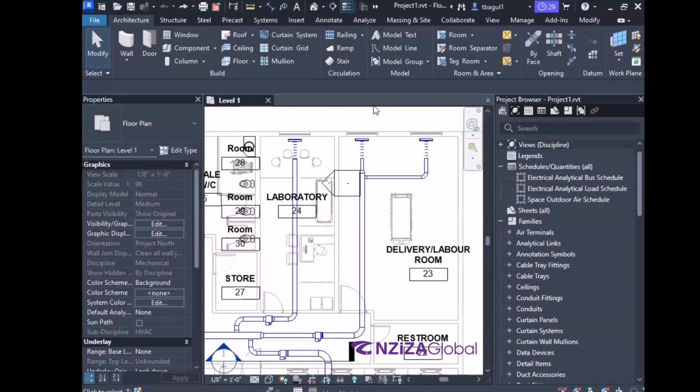If you try to capture those heat loads right at the facade, your AC system will not need to work overtime as compared to if you have the diffuser over here, because the real heat load is coming from these two areas. And in that case too, try to center it over the windows, because as we mentioned, windows will have the most amount of heat transfer coming into a given area.